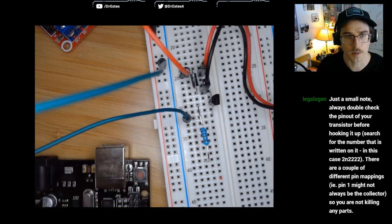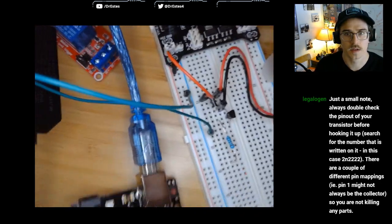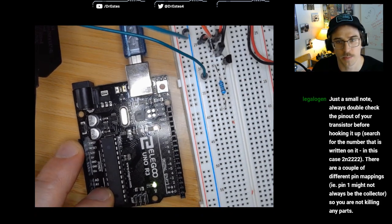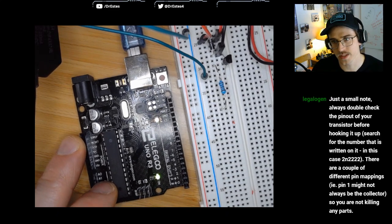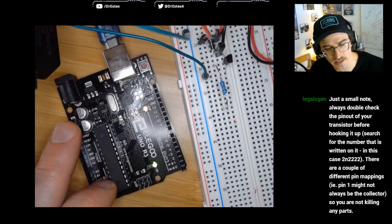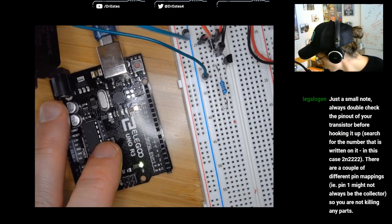And then on my Arduino, let's plug this in. Oh, just a small note, double check the pinout of your transistor. Yes, that's a very good point. The collector, emitter, and base, it's not always going to be the same. Transistors like these are going to have 3 legs, but you always want to look up the specific data sheet to be sure which one is the emitter, which one's the collector, because that does matter. Thanks so much for throwing that in there.